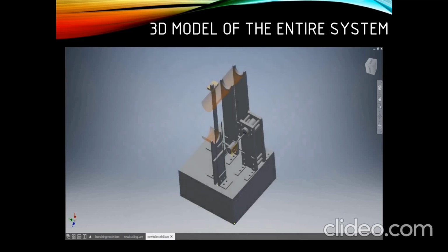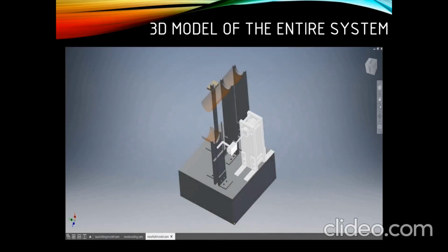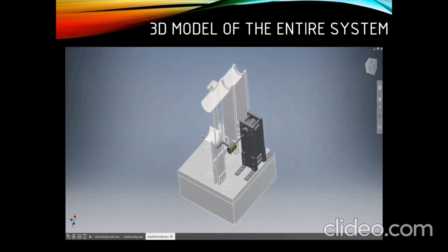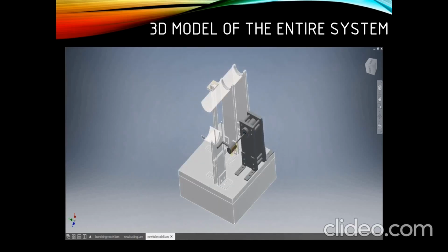Once the barrier is lifted, one ball slides through this tray and falls into this holding tray. At the same time, this L clamp will pull the spokes till it loses contact with it. Because this hinge is wound with the help of a rubber band around the T-shaped structure, once this clamp loses contact with this, the T-spokes are launched forward and they exert a force on the ball which helps in its launching.